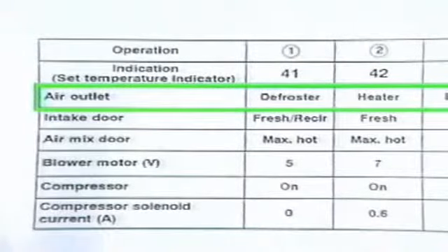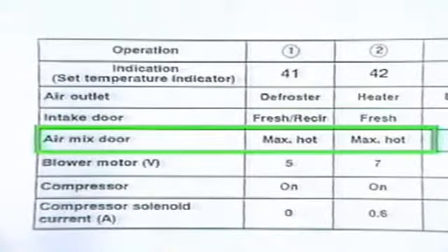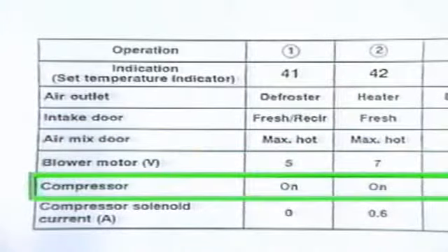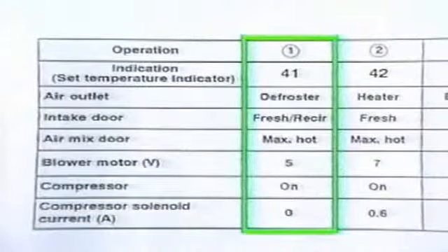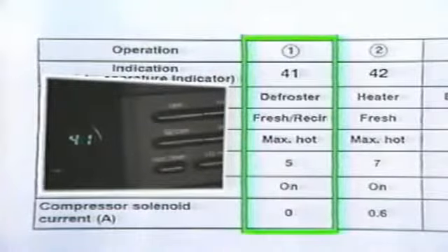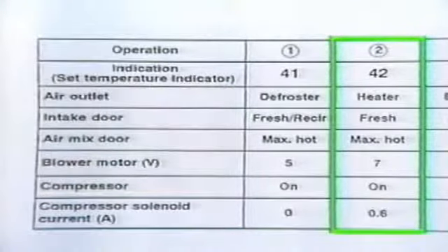Following the fault code display mode, the output signal recognition mode is accessed by depressing the auto switch one time. The defrost LED and mode 41 are displayed. The ACU program has 6 predetermined output signals which are sent to the HVAC system controls during this mode. The control HVAC components should respond as shown in the service manual. To advance through the 5 output signal recognition modes, depress the defrost switch. To return to the fault code display mode, press the auto switch one time.